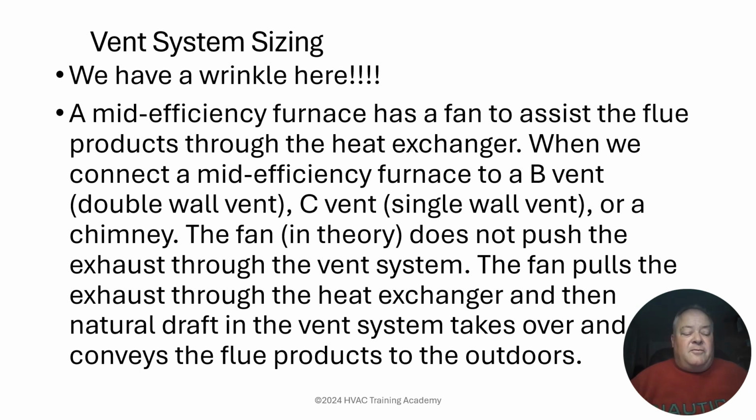And I know the company I worked for at the time, we put an awful lot of these pieces of equipment in using the specialized plastic sidewall venting. What they found is that the actual venting system started to fall apart and erode mainly at the joints, where they would just basically fall apart. So it was decided very quickly into the tenure of this sidewall venting of mid-efficiency furnaces that they would discontinue that type of a vent system for the mid-efficiency furnace.